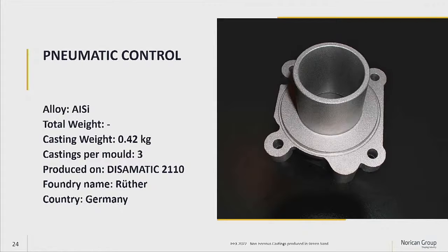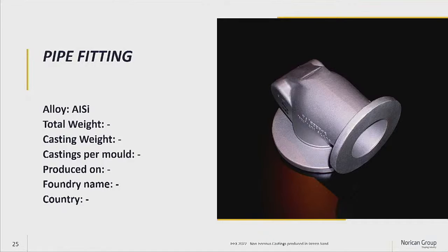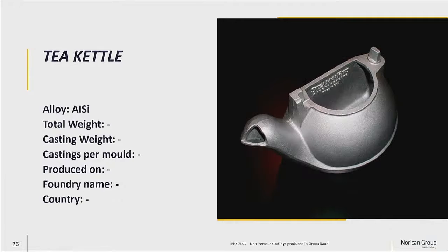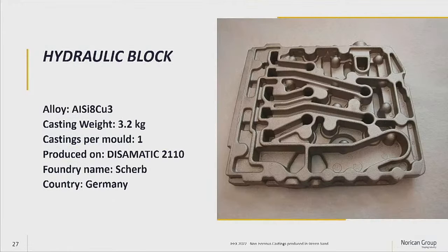This casting will demand pressure tightness. Another casting that will demand pressure tightness. We can also do aesthetic castings. If we take a little bit more care about the sand parameters, we can reach super good casting surfaces. So even aesthetic castings can also be produced in green sand.